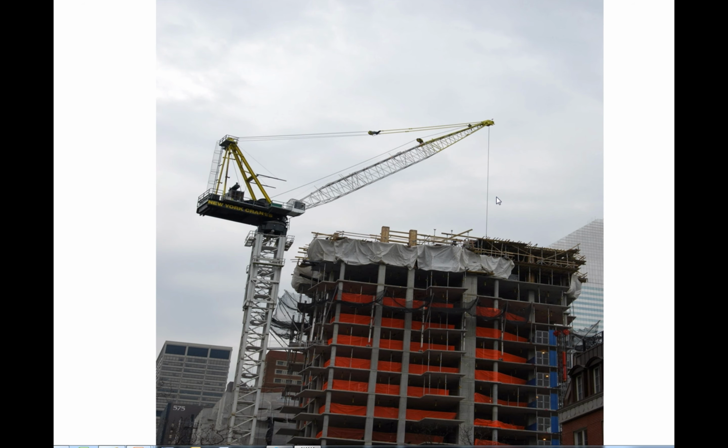And what that is, is a tie-off for those who have to use fall protection to work at the edge of the building. So anyone that has to come within the edge of that building should have a full safety harness and lanyard that they can just clip right onto that. That's embedded into the concrete floor, and it's part of the production in the factory for those sections of concrete floor. So when it comes to site, it's already there.